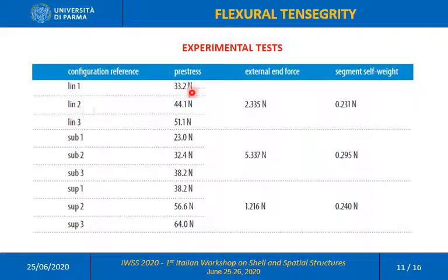Of course, these are just the initial pre-stress, and then the tensile force in the cable may vary because of its elongation consequent to the deformation of the beam.